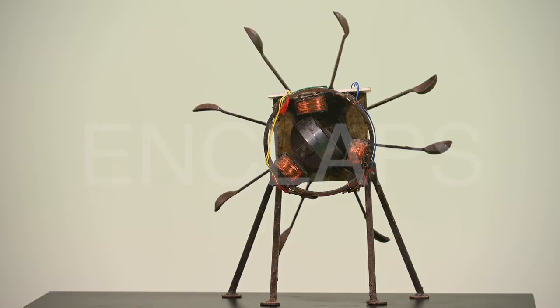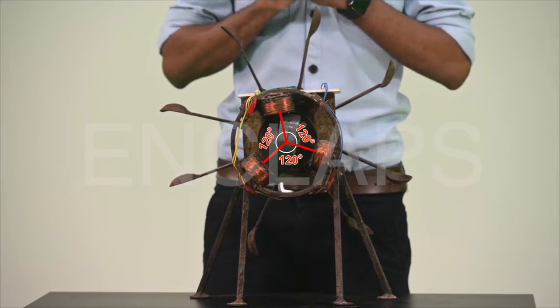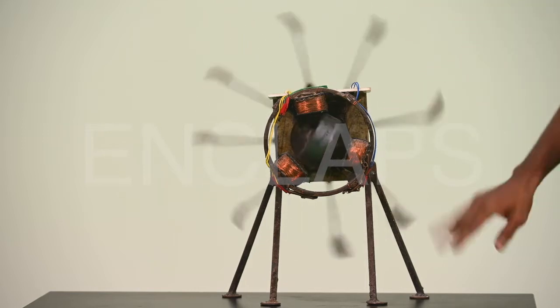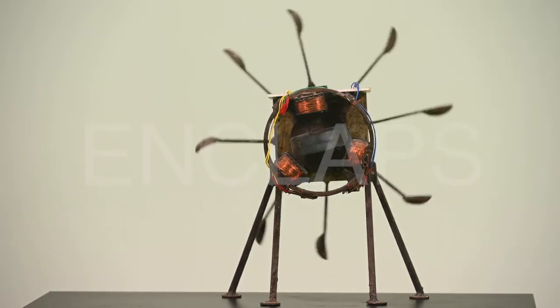This is the working model of a three-phase AC generator which can be seen in hydroelectric power stations. Here, the 3 armature coils are arranged around the field magnet at an angular separation of 120 degrees. This is the motionless part of the generator. Thus, it is called the stationary part or stator. Another important part of this is the field magnet connected to the turbine. When the water reaches the turbine, it rotates, which causes the rotation of the field magnet. Therefore, the field magnet in the generator is called the rotating part or rotor.